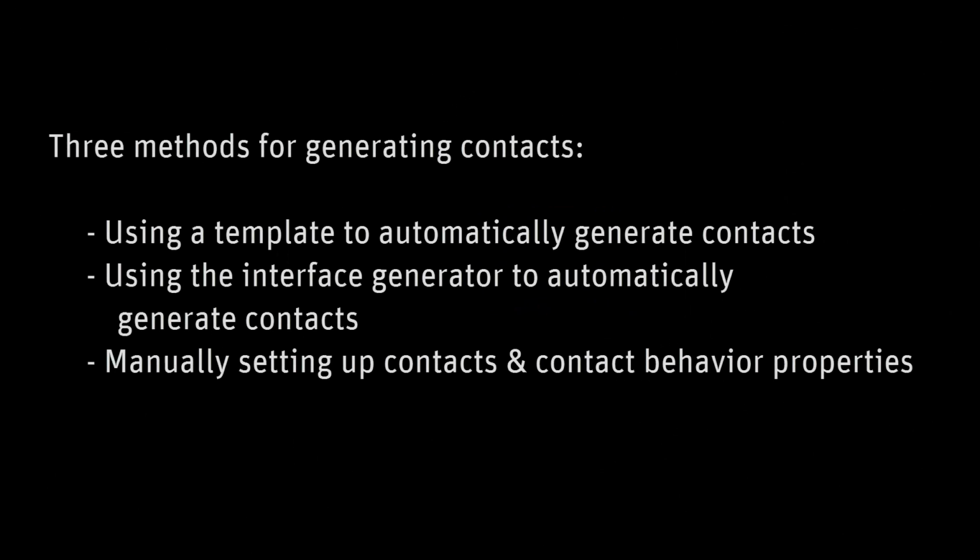In this demonstration, you'll learn how to generate contacts using 3 different methods. The first 2 are automatic, using a template or the interface generator. The third method is to manually set up contacts and modify contact properties.